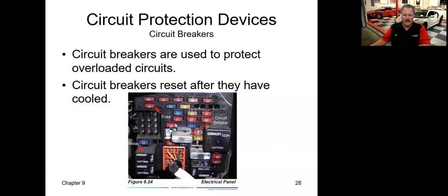There's one right there. There are your fuses in the fuse box right there. You've got a 10 amp fuse and that fuse blows, folks. Don't go reaching for a 15 or a 20 amp fuse to put in the 10 amp fuse spot. Whatever that fuse was protecting down the line may end up getting shorted out and destroyed, like maybe a very expensive radio, for example. Or maybe there's a fan motor that's shorted out and you're allowing current to go to it. You could end up with an electrical fire underneath the dash. So just replace a 10 amp fuse with a 10 amp fuse and a 15 amp fuse with a 15 amp fuse, okay?